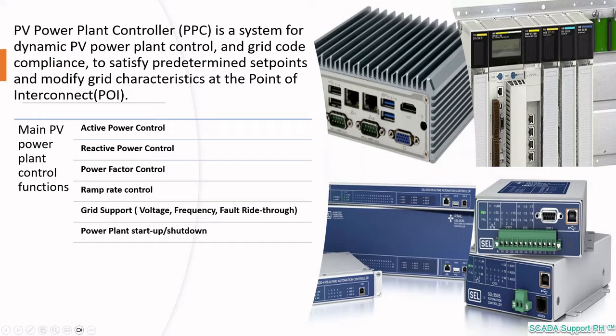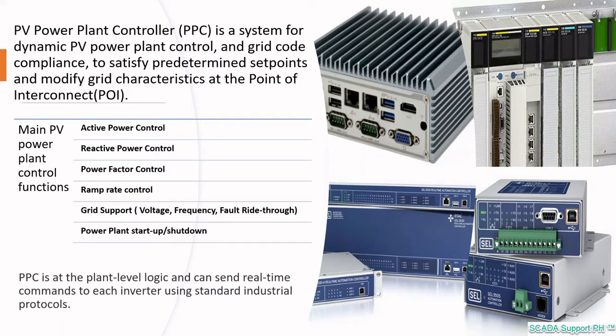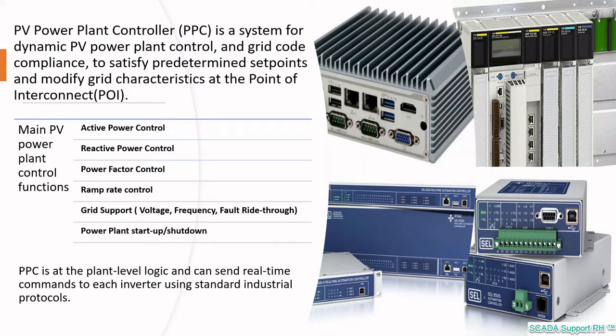The PV power plant controller is to be implemented at the plant level logic and utilizes closed-loop control schemes. Real-time commands will then be sent to each inverter via industrial protocols such as Modbus RTU or TCP, DNP3, IEC 61850, or IEC 60870, and the like.